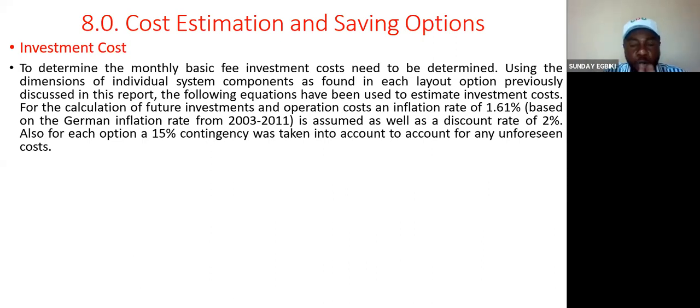called as a consultant to come and design a water distribution system: 1, site visit and survey information. 2, house density and population projection. 3, localization and water demand estimation. 4, localization and pressure zoning.